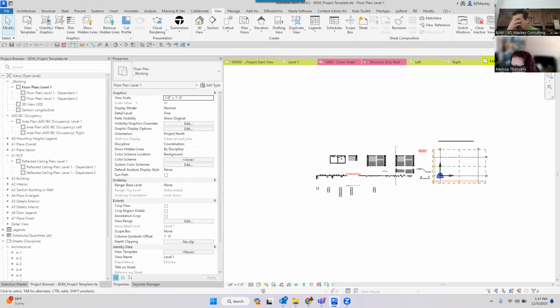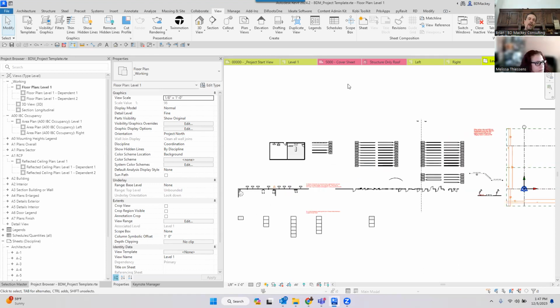I know there's add-in utilities out there. I think there's one called Synchronizer or something like that. I know a lot of people have Dynamo scripts. I think somebody was telling me that the CTC tools will do something like that too. I don't remember, but natively, no. All you can do is tab select, copy to clipboard, paste, or open up that file, copy them all to the clipboard in the same session of Revit, and then paste them into your project, same location. Of course, that also assumes you have the same project location and project orientation. So unfortunately, no, there's no tool to automatically copy those.